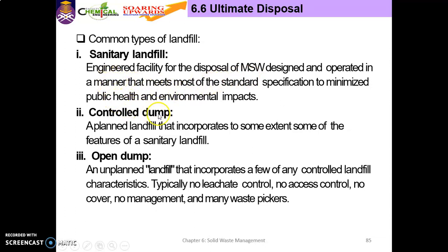Number 2, controlled dump, a well-planned landfill that incorporates some of the features of a sanitary landfill. And also open dump, an unplanned landfill where you just dump all the solid waste, incorporating few of the controlled landfill characteristics. Since it is unplanned, there is no leachate control, no access control, no cover, no management, and many waste pickers.